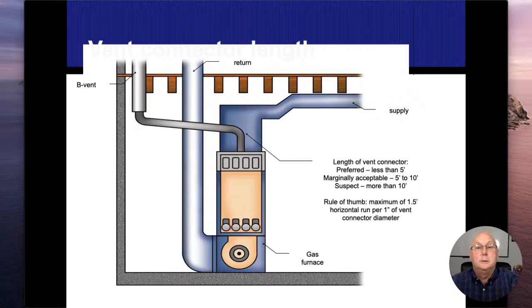It was the case. So what I ended up doing was disconnecting the water heater vent connector where it went into the chimney. I put a flashlight in there. I went into the firebox and looked up the smoke chamber and looked up the flue. And sure enough, there was my beam right there from my flashlight. It was definitely coming right inside there. So there was no damage. The measurements worked out fine. There was only one flue going up and out the top. All the signs said, yeah, this is going in there.